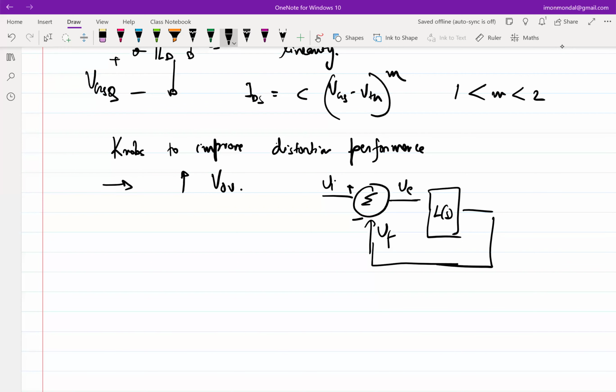And that is a far more difficult thing to achieve at higher frequencies because phase starts to roll off pretty quickly, right? That is why if you are doing multi-gigahertz design, it's difficult to use feedback. So introducing negative feedback obviously is a generic hack that one might want to explore, but at high frequency it's a problem.